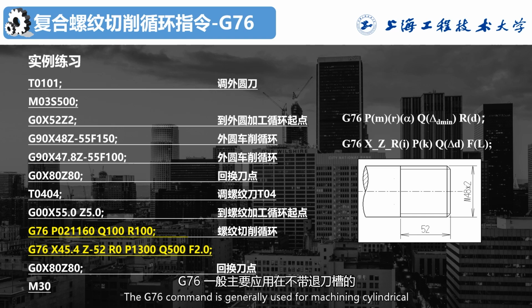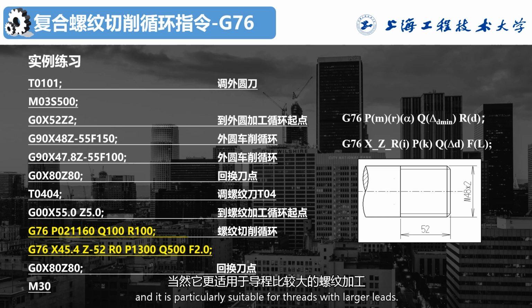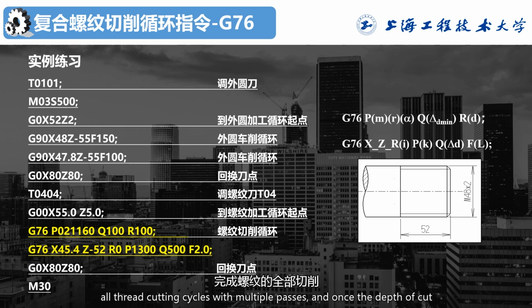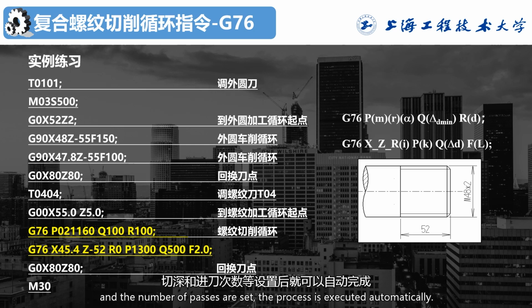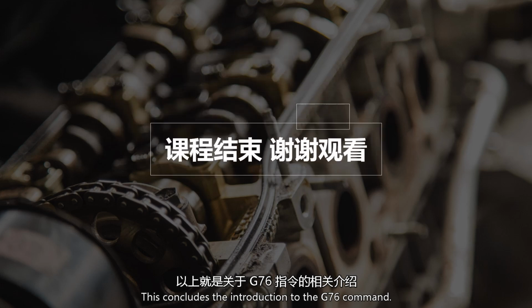The G76 command is generally used for machining cylindrical and tapered threads without relief grooves, and it is particularly suitable for threads with larger lengths. The G76 command can automatically complete all thread cutting cycles with multiple passes, and once the depth of cut and the number of passes are set, the process is executed automatically. This concludes the introduction to the G76 command.